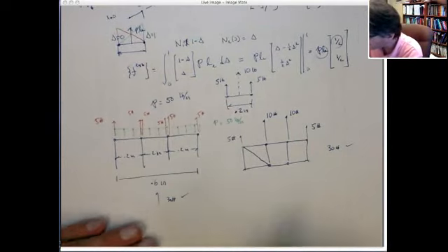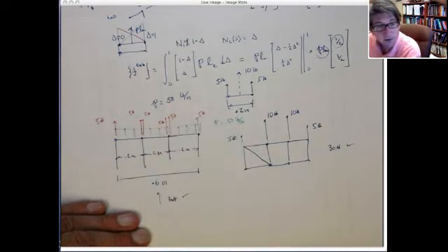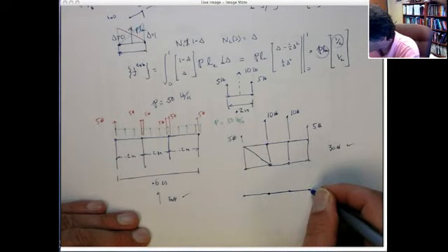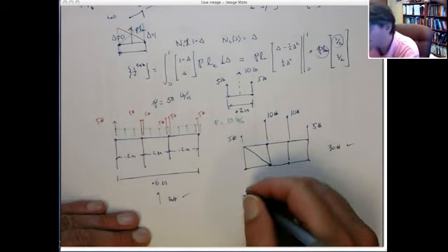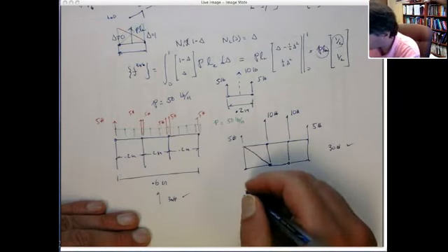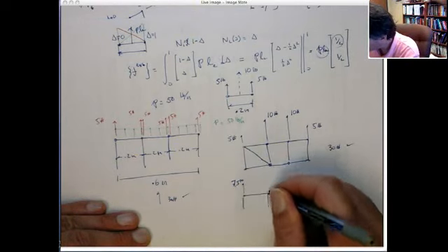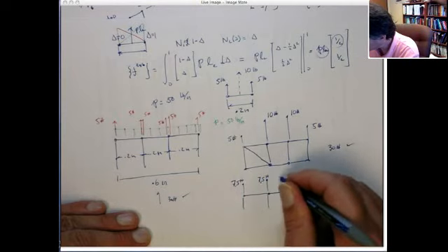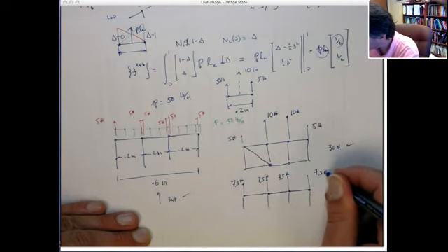So what you don't want to do, what would be incorrect, is to say, okay, we have a total of 30 pounds on this edge. I'm going to divide that evenly up between the 4 nodes. So that would be, well, 30 divided by 4 would be 7.5 on each, right? 7.5 pounds, 7.5 pounds, 7.5 pounds, 7.5 pounds.